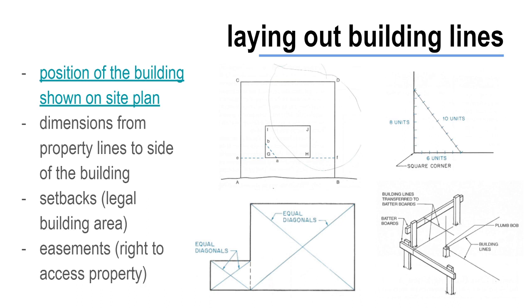Typically you'll find easements related to utilities. So there might be an easement related to the Public Works Department being able to access water lines, or for New River or Blue Ridge to be able to access power lines on your property. That means I can't build anywhere on that area that Blue Ridge is allowed to access to do maintenance for their power lines, because if I built something there, they then have the right to tear it down and get rid of it.